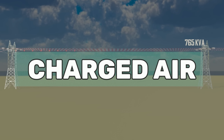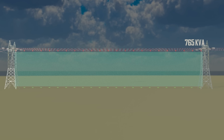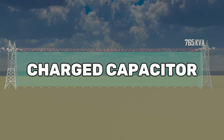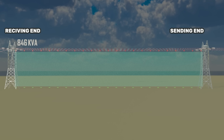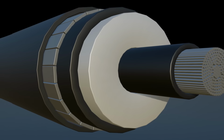In this condition, the line conductor behaves like a positive plate, while the ground behaves like a negative plate. This creates an effect similar to a charged capacitor. This capacitive interference can increase the voltage at the receiving end, meaning the received voltage may become higher than the voltage originally sent. Now look at the cable.